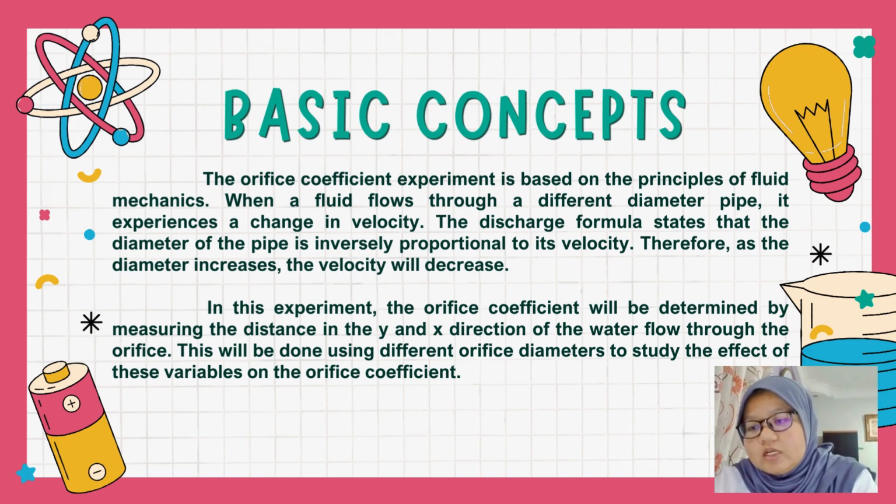In this experiment, the orifice coefficient will be determined by measuring the distance in the y and x directions of the water flow through the orifice. This will be done using different orifice diameters to study the effect of that variable on the orifice coefficient.